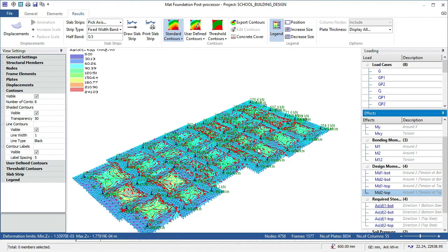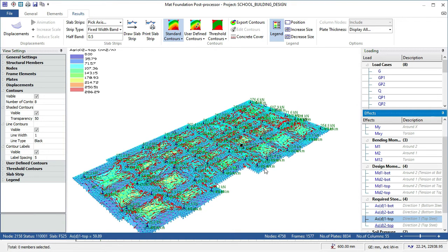As you're clicking here, if your slab depth was not sufficient, you will be seeing an error. Once you get to this area of steel stage, if your slab thickness is not sufficient, you will begin to see errors like insufficient depth errors. So once you see that kind of error, you have to go and locate that slab and then increase the slab thickness, or increase the thickness generally for raft foundations. Okay, so I will go again.